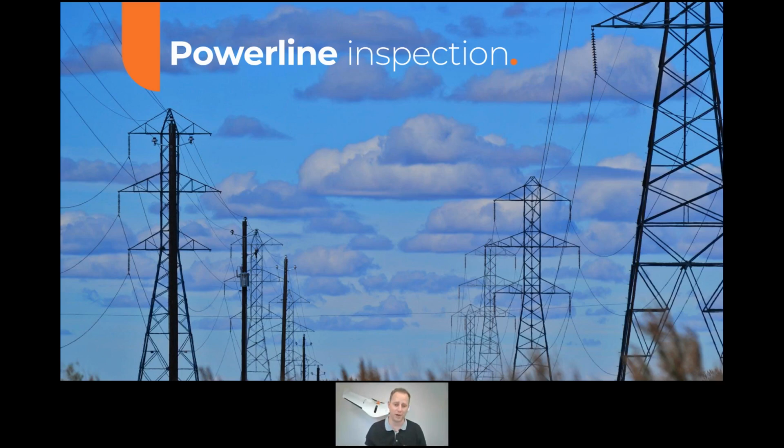So we can monitor our vegetation encroachment, or we can look at defects on our lines or insulators, where we can look at other problems and take other measurements, just do general survey work. And so now we can take off in the middle. We can fly 10 or 20 kilometers in one direction and then back the other way in 10 or 20 kilometers. So we can feasibly map 20, 25 kilometers with overlap in a single flight, all while maintaining really good communication strength and not sacrificing any kind of safety or concerns around our data quality, because we can see that live map the whole time.